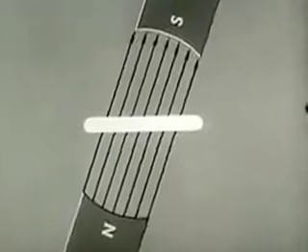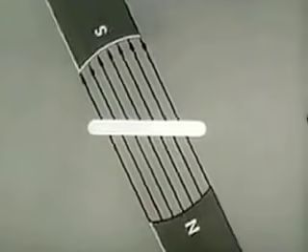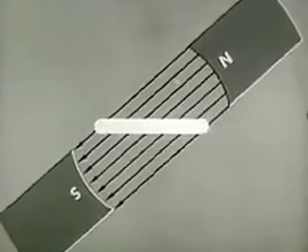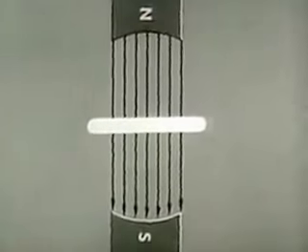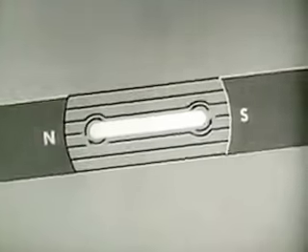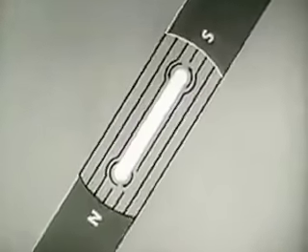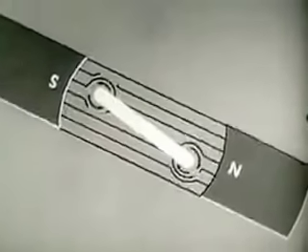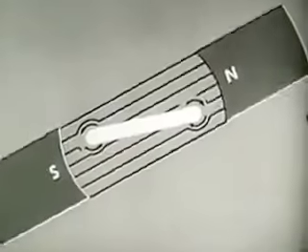This, however, is an impossible situation, for if the rotor stops while the field continues to turn, relative motion will have been re-established. Lines of force are being cut once more. An EMF is generated and the resultant magnetic field will cause the rotor to move again. So far, we have rotated the field by physical means, which is impractical.